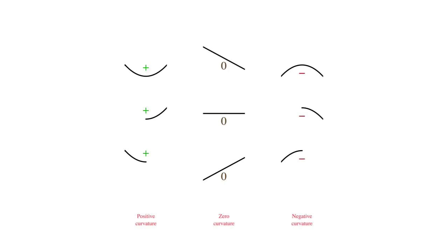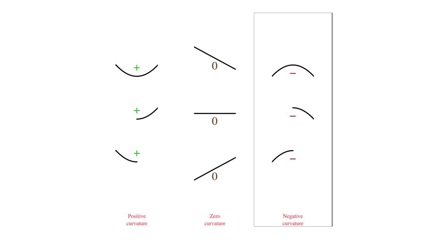This theoretical shape matches the deformed straw, and yes, we again get a good match, this time between theory and sketch. Before moving on, we need a little terminology and a sign convention. In particular, we want to talk about curvature. Curvature is approximately the slope of the slope, or the second derivative of the displacement curve. As a convention, we will consider a decreasing slope to be negative curvature. It looks like a frown or a half frown.